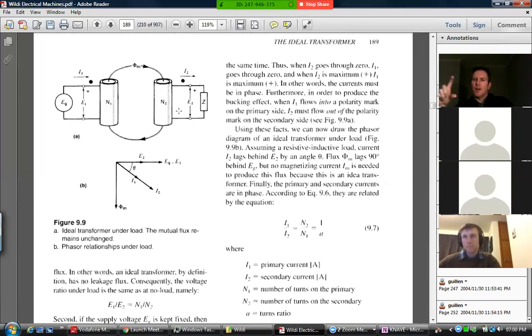So the V is the same, the I is going up as the resistance comes down, so a small resistor is actually a large load. If you keep connecting light bulbs in parallel over here, you're making a smaller resistor, and you're getting more and more current sucked in over here.